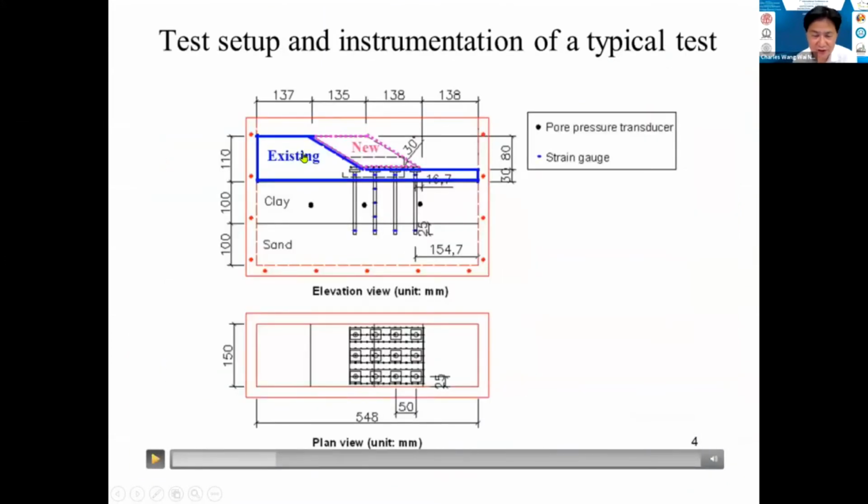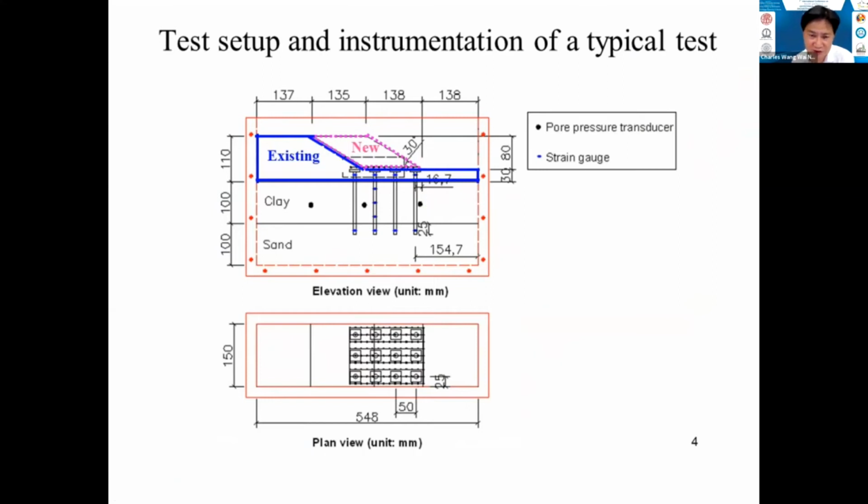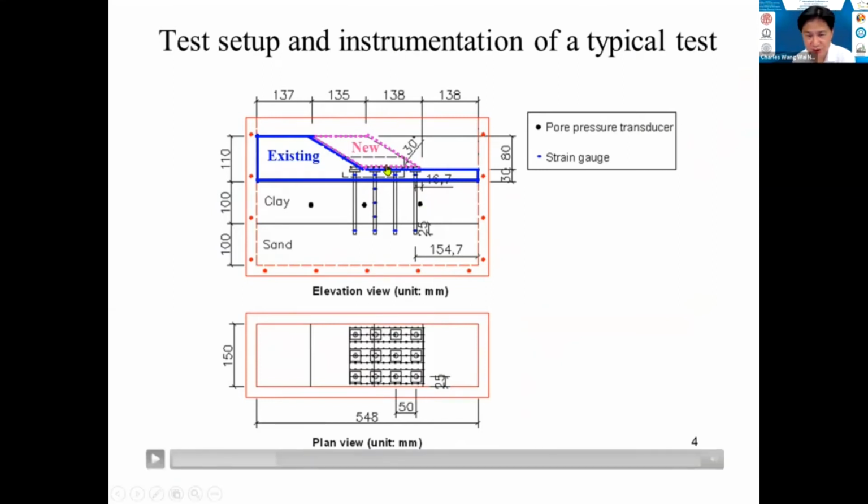We all know that in order to widen an embankment, very often we put piles to support this new part of the embankment, and the piles try to minimize the settlement of the new part of the embankment caused by the consolidation of soil clay underneath. So now the question is, what should be the pile spacing, for instance, and should we use a geomembrane, and so on and so forth?